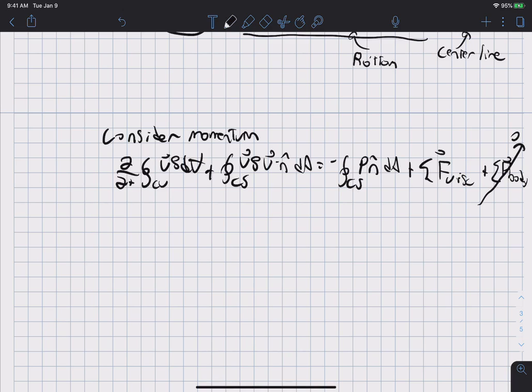Okay, we're going to neglect the body forces. We're going to assume steady flow. And since we're including viscous effects, we must include the viscous stresses. We have to include pressure. And now this term here, we are assuming fully developed flow. So this term actually goes away. If it's fully developed flow, that term goes away.